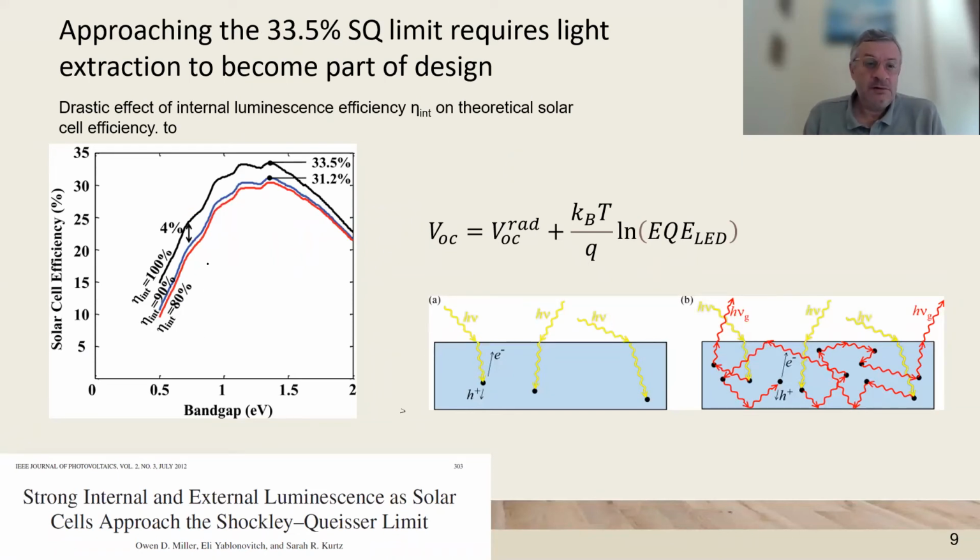If the internal quantum efficiency decreases, then the overall efficiency decreases. In general, having a high luminescence efficiency is an indicator that you have a high density of electrons inside the solar cell at a given incoming light intensity, so this indicates a good efficiency.